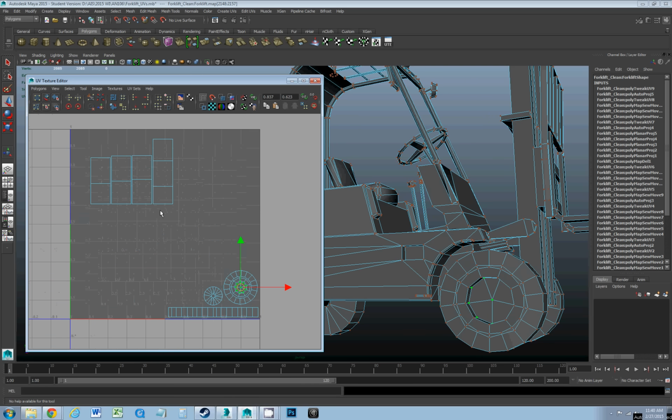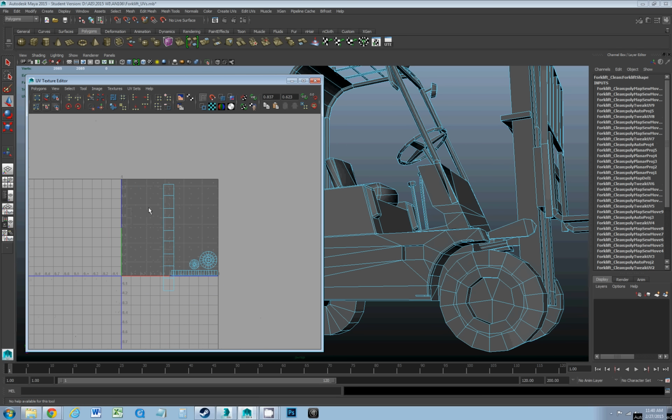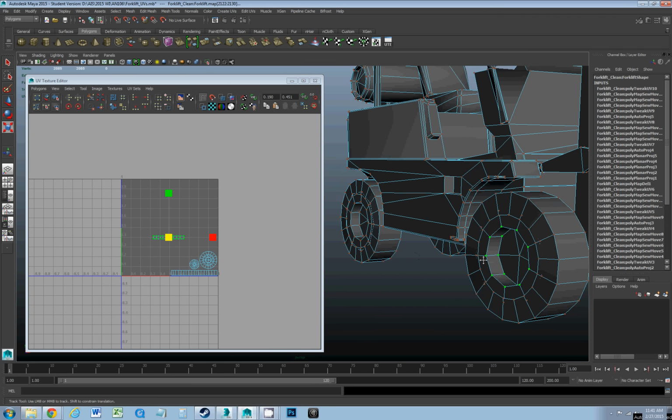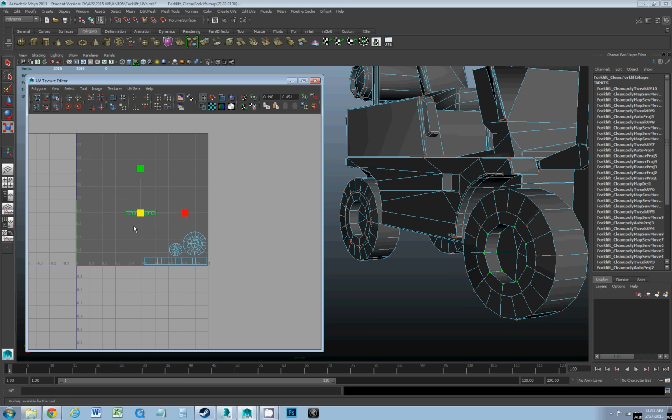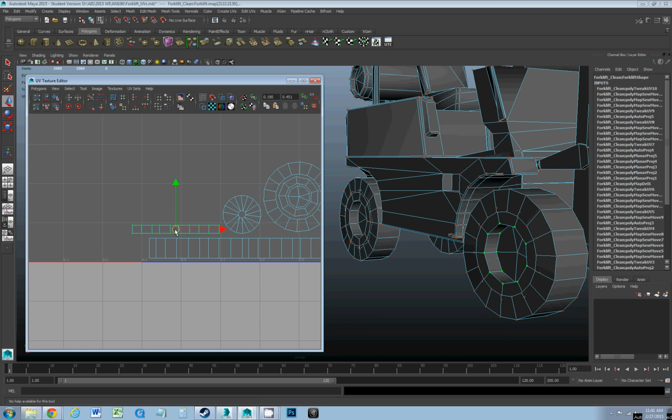And then it's the same thing here. I'll go to edge, grab that, hit move and sew, grab that. You can see how quickly I can move. And then I'll grab that whole shell and then knock it over, hit R for scale. And this piece is the inside of that rim, so it doesn't need to be as big as the tread. Scale that down, and let's move this someplace sensible, maybe like that.